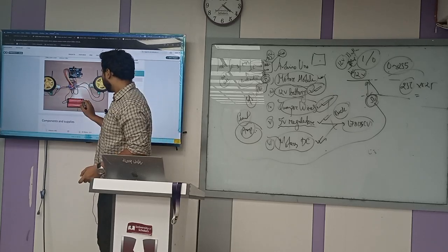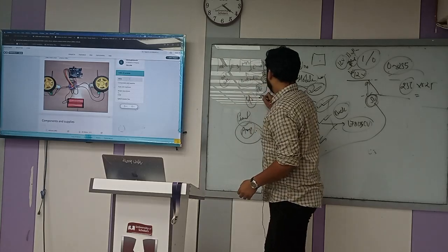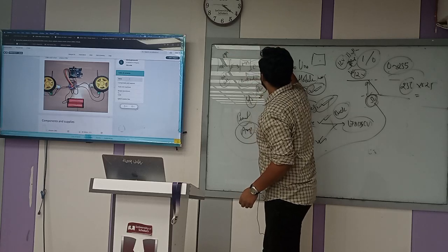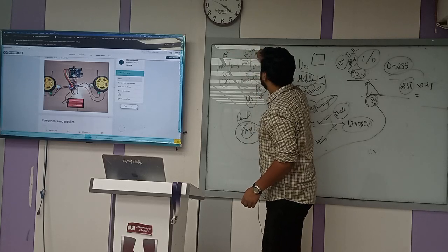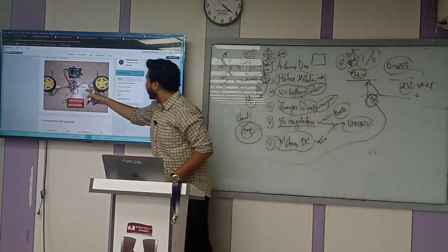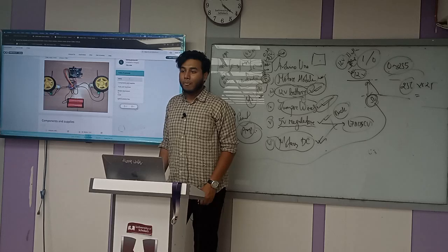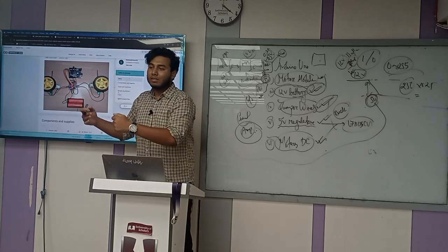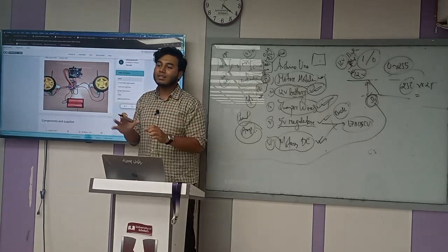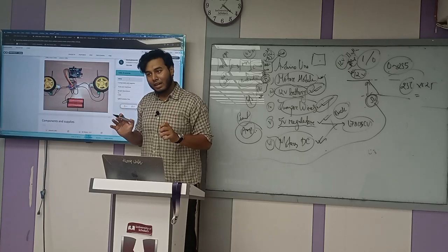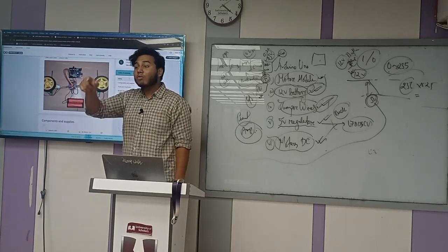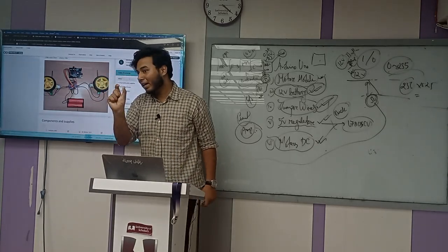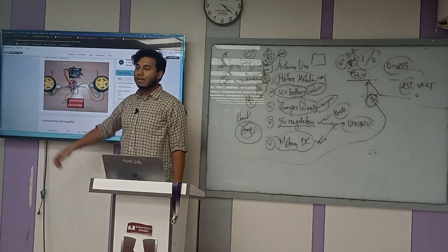You get my point? Let's see, it has 2 ampere. If the motor consumes 0.9 ampere, then only 0.2 ampere will be left. So this 0.2 ampere will be passed to that Arduino. As we can understand, the Arduino takes a very low amount of current, but why should we take a risk? We should give a proper connection as we are electrical engineers. Okay, so we are not going to use this thing. Better we buy a buck module or the L7805CV IC with a heatsink. Then we will connect this Arduino.